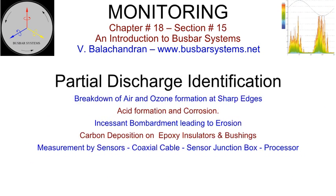Partial discharge identification. In an isolated phase bus, partial discharge can take place wherever the electrical field on the surface of the conductor exceeds the breakdown voltage of the surrounding air. Sharp edges, such as on the fixings, laminates, terminals, and conductor castings, are potential locations.